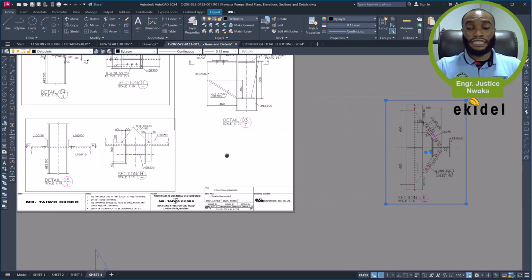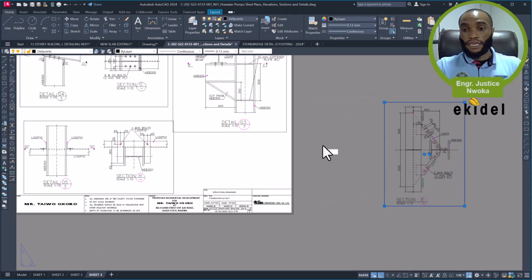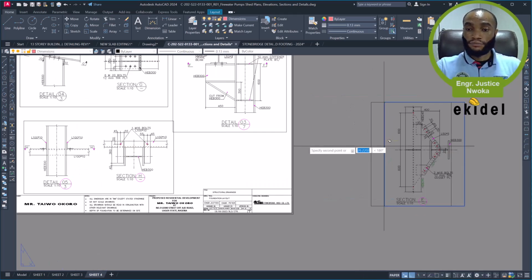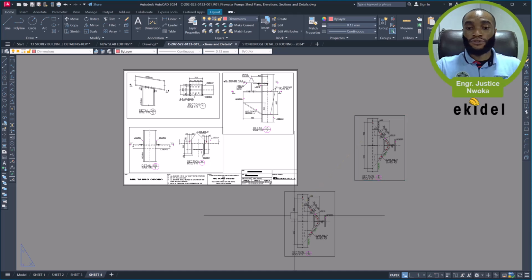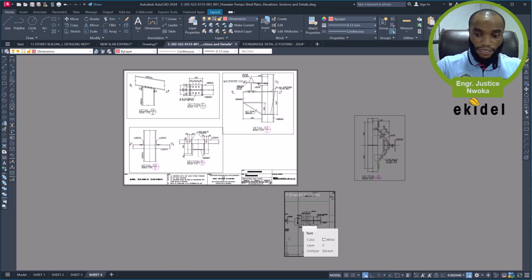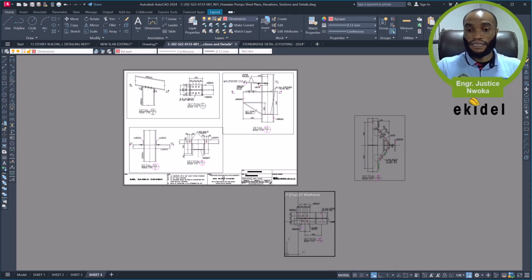So I'll copy again right now this one. Okay, and then keep this here, and then check inside the viewport to see if I can bring in a drawing that can fit in. Okay, this one can fit in perfectly, this one here. So I type Z, enter, 1/10 SP, enter. Okay, that's fine. Yeah, correct, it can fit in there. So I'll come now, position it with this, press PX.